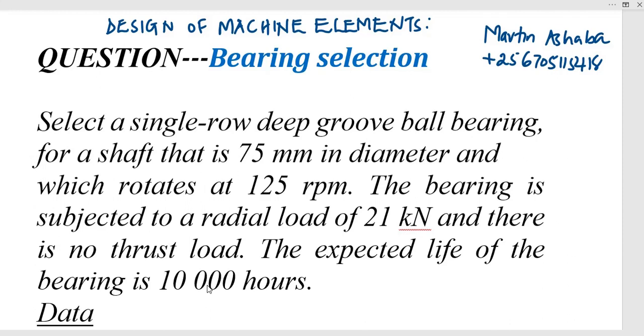So in this particular video, during the process of bearing selection, you already know which diameter you need, because you already have the diameter of the shaft. But if you don't have it, then during the process you have to determine it. After knowing the diameter of the shaft, you are able to tell the diameter of the bearing, then you know these other prevailing conditions, then you go ahead and follow the known procedure to select that bearing. This is a single row deep groove ball bearing.